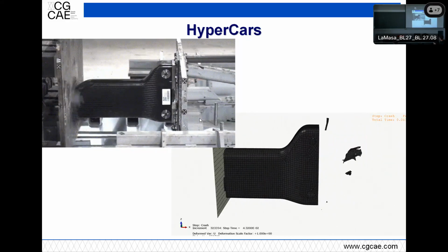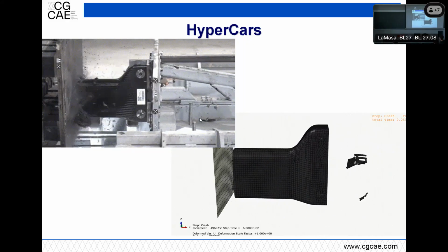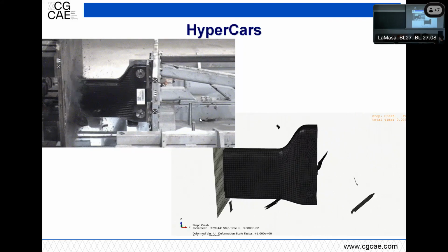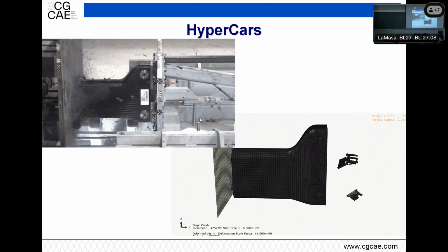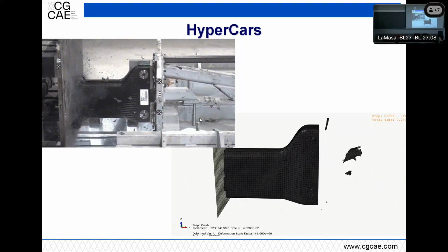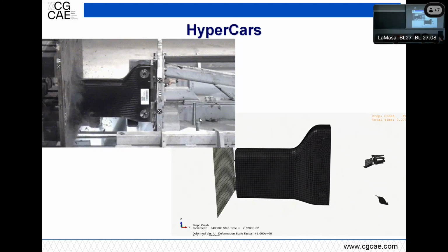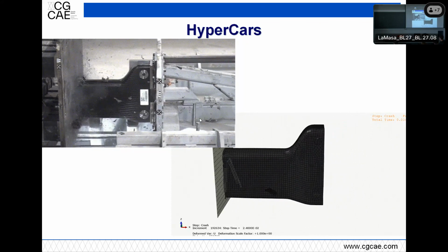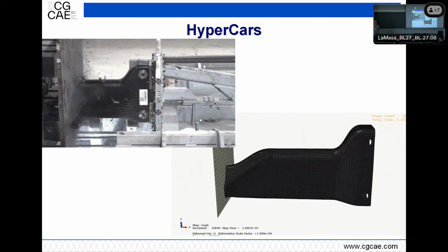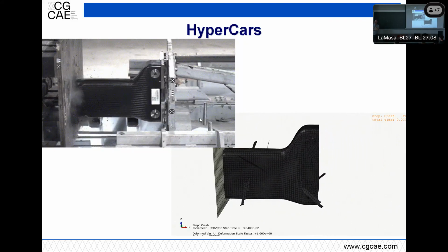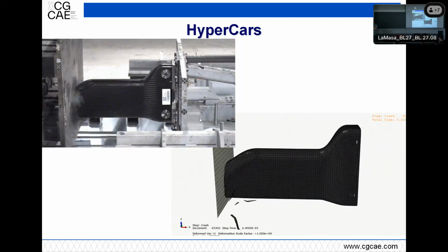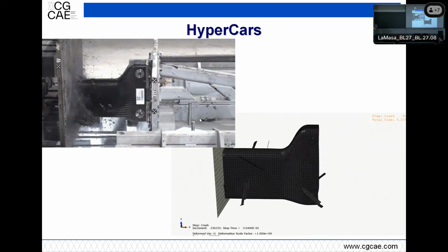Maybe these belts, hubs, which you anyway see some 1,000 cycles, even on short mileage, you do that. But it's not really a real issue with static, the safety factor for static, which is not that high or that low. Sometimes 1.25, some feel better with 1.5, and this, given the number of cycles that you see, is enough to cover fatigue also.